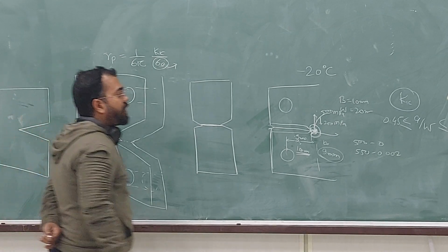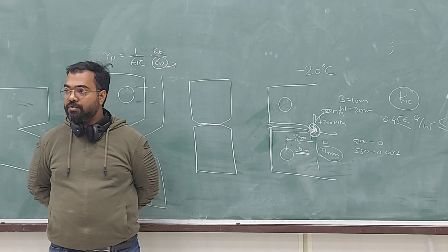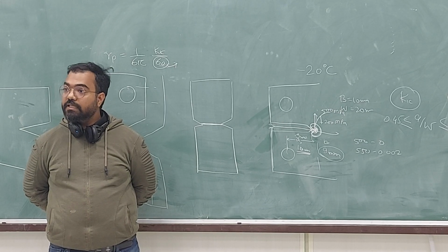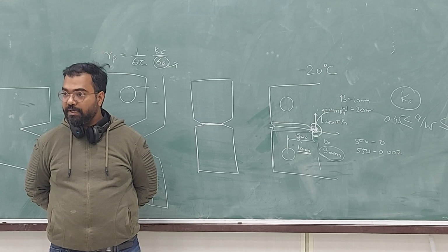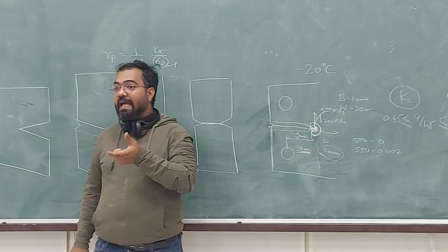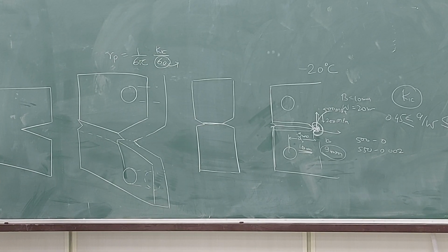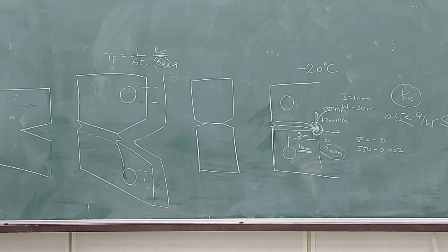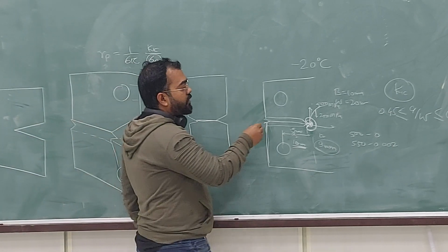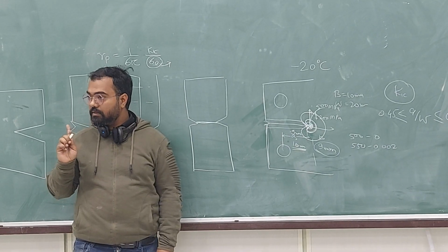So this plastically deformed region, which is created in the fatigue pre-cracking stage, is deformed at a certain value of stress. As you go down in temperature, yield strength is increasing. So this deformed region will act as if there is a residual stress in the material. It has already strained, so it will try to close the gap. So for monotonic loading, you need to have a plastic zone at least larger than this. It cannot be smaller than this. Do you understand?